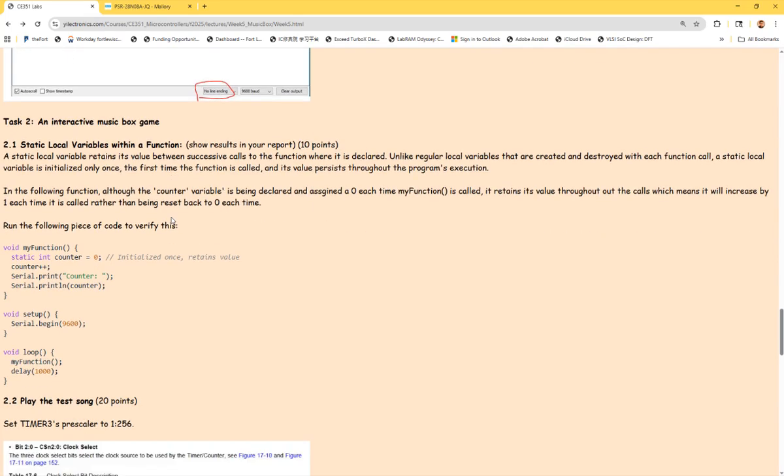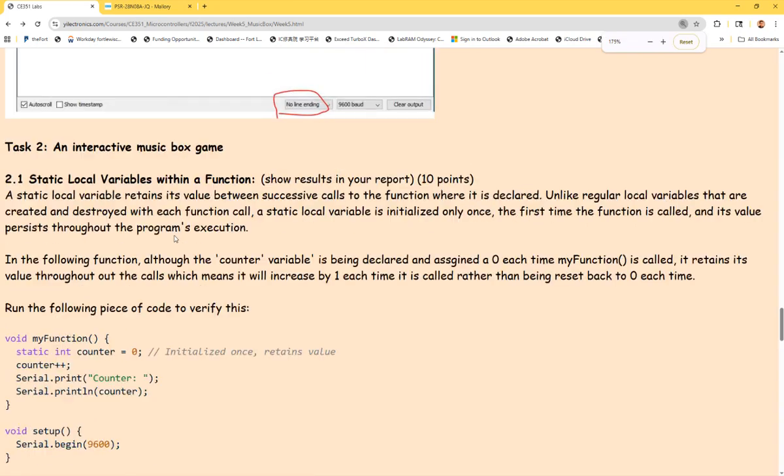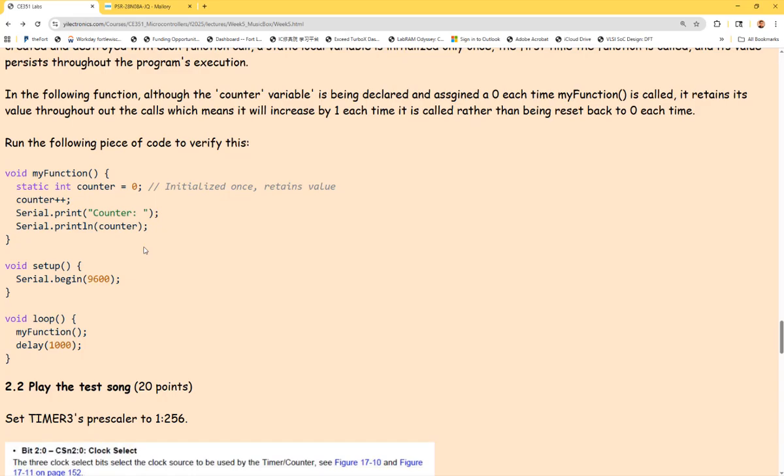And here, static function. I can spend 2 minutes to get this done easily. So by looking at this function, this is executable. You can directly copy and paste it to Arduino and connect the USB to the computer. You should be able to see something from the serial monitor. And here's the setup function. It just sets up the UART, right? And then the loop function starts running, and the loop function doesn't do anything but call this sub function. So my sub function is over here.